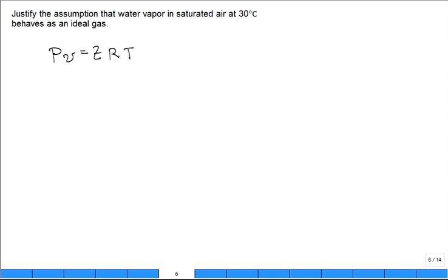It's a compressibility factor, Z, which says that you have the pressure, then you have the specific volume divided by RT. And if that's close to 1, then we say we have justified the use of the ideal gas equation. Then we would throw out the Z, and you would just have PV is equal to RT.